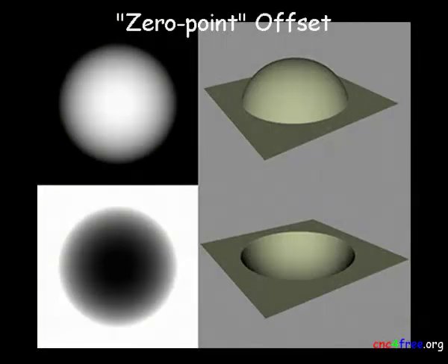Height maps can manipulate or offset the 0 position. This is similar to the way CNC machine 0 point can be adjusted to suit job requirements. For example, where penetration of the surface below the 0 position is not required, black can be treated as 0. This doubles the range of available gray values in the positive direction to produce a smoother convex surface. Where surface protrusion above the 0 position is not required, white can be treated as 0. This doubles the range of available gray values in the negative direction to produce a smoother concave surface.